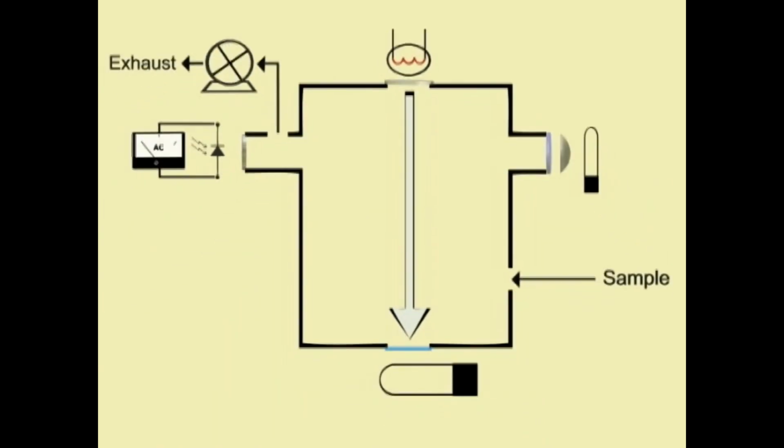An independent light source is used as an optical test device. This is usually an LED or an incandescent lamp. When activated, this device simulates the light that would normally be produced by SO2 fluorescence. This is very useful in testing the PMT as well as any associated electronics. If an otherwise non-functional analyzer responds to the optic test device, then the problem must be pneumatic in nature.